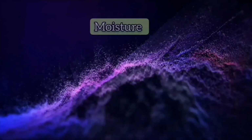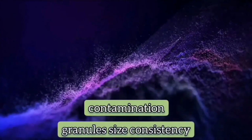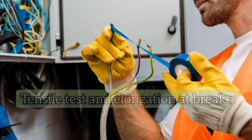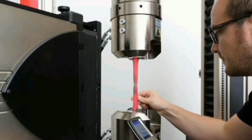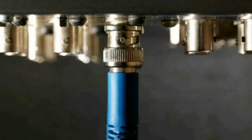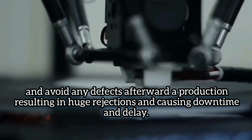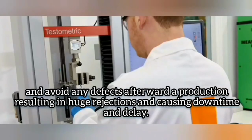Visual aspects such as moisture, color, porosity, contamination and granule size consistency are checked using our microscope. Tensile strength and elongation at break: last but not least, tensile test machines are used for evaluating the strength and elongation properties of plastics. This test is one of the most important tests to determine and avoid any defects afterward in production, resulting in huge rejections and causing downtime and delay.